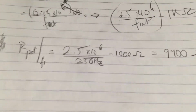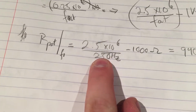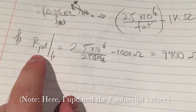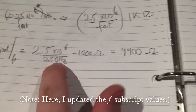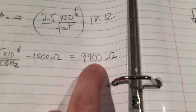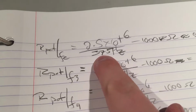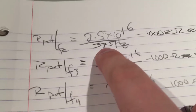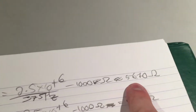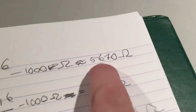Now that I had settled on the desired pitches for each respective key, I substituted these values into the equation I came up with before. So the first value, for the fundamental frequency of 250 hertz, is 9400 ohms, roughly. Actually, in this case, it worked out to be exactly 9400 ohms. For the second one, which would be 3/2 times the fundamental, or 375 hertz, I ended up needing a value for my potentiometer of approximately 5670 ohms.